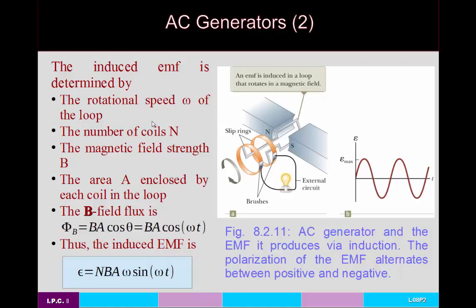And in fact, as you make a complete revolution, you will flip the direction in which the flux is changing. So for example, you're initially decreasing until you get to zero flux, and then suddenly you're increasing, which means that the current needs to be induced in the opposite direction, and then it starts increasing. Both the flux and the rate of change of the flux will be increasing or decreasing together. And so you end up getting an alternating current signal.